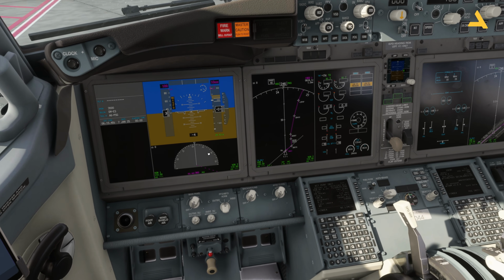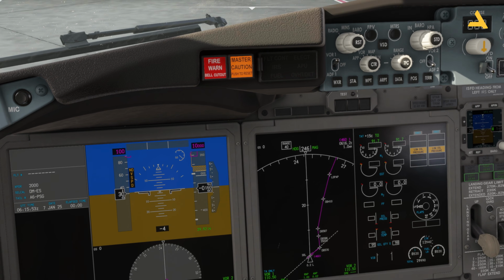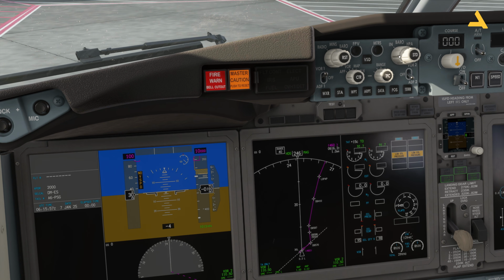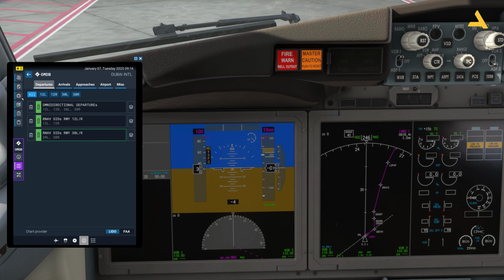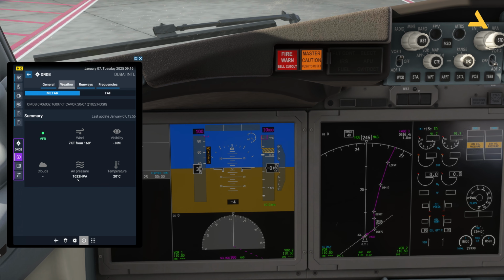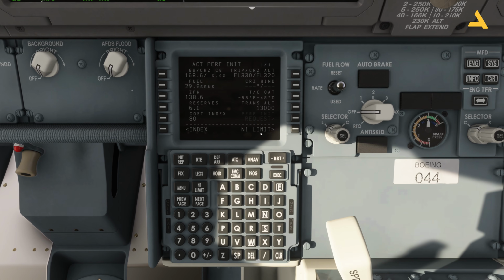So this is the barometric pressure. Right now it's 29.92 in inches. You can change it to HPA by moving this knob. So it's 1013. And currently in Dubai, it's 1022. So you can move this knob, the smaller one, and adjust the altimeter. The planes get the altitude based on the barometric pressure, so that's why you have to adjust the barometric pressure to get the right altimeter readings. That's it. So this is the altitude at which I will change it from the given one to the standard.